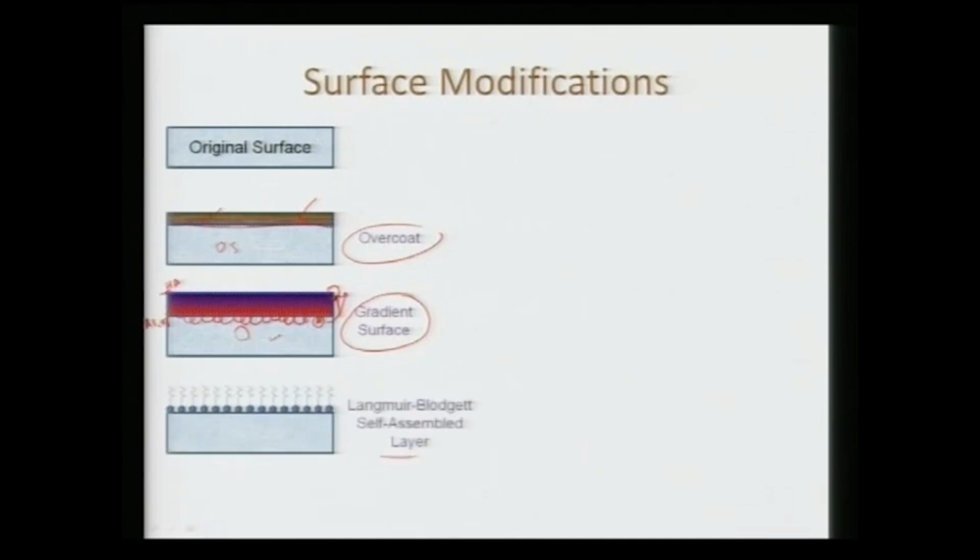and we can also apply certain self assembled layers. These are called Langmuir-Blodgett self assembled layers. So, we can provide certain functionality to the surface. We can let the polar head groups stick on the surface, and that can basically stick to the fluidic region. So, the polar head region will be much more hydrophilic in nature, whereas hydrophobic regions can stay outside, so that it will reduce the overall wetting of the surface.